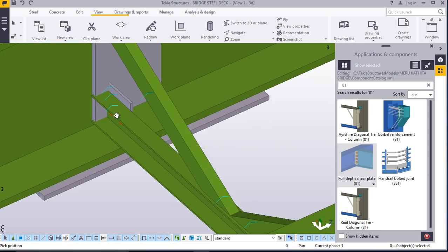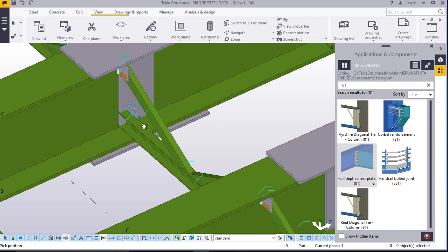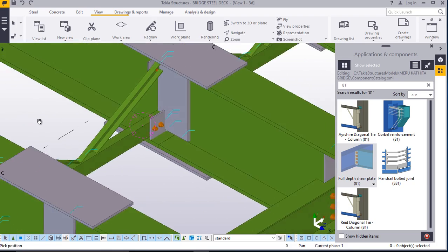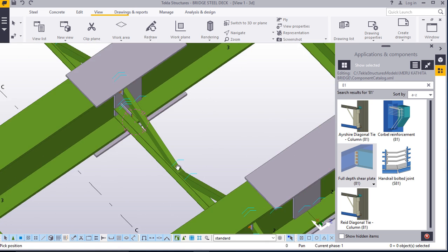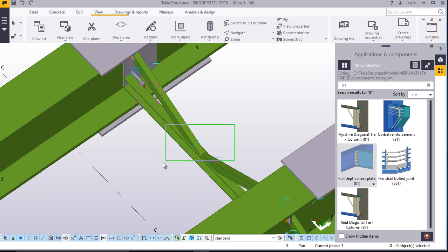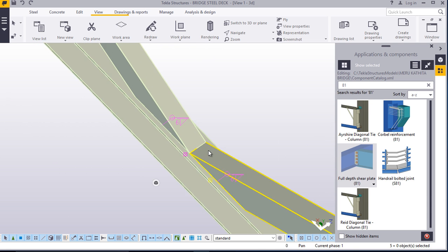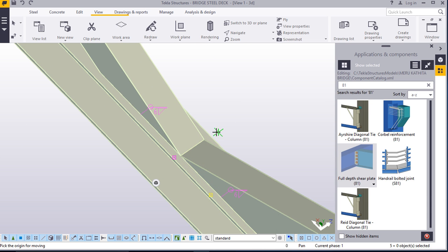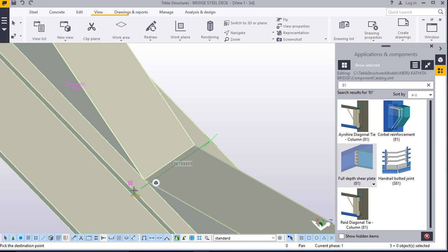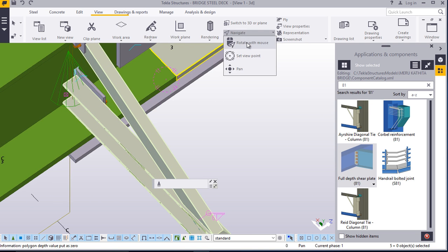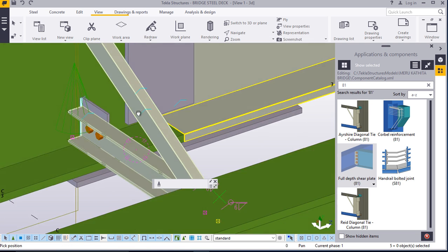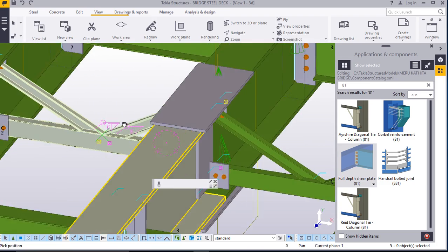But not properly done here on the joint. This connection should not be touching this joint at all. What we are going to do is to give an offset for every bracing. Click, highlight everything there, right click, move, snap there and snap here, and type 300. It has moved away. It has moved away.